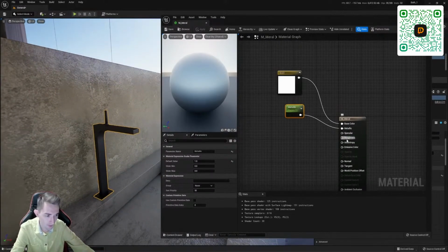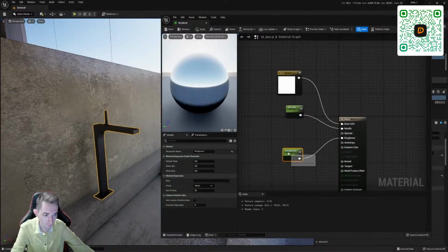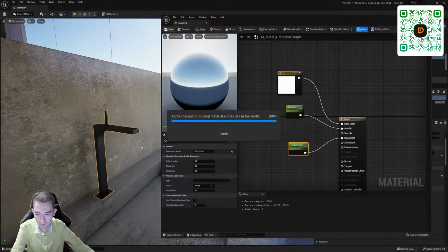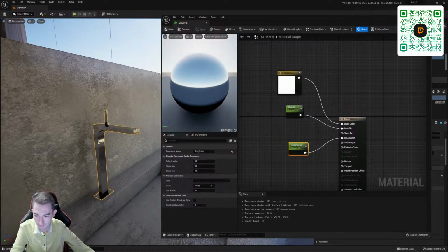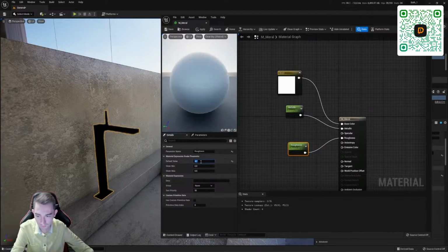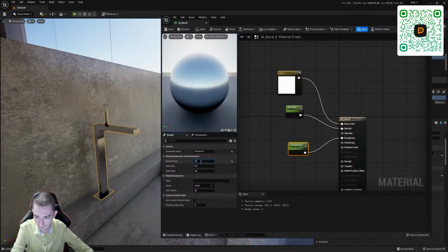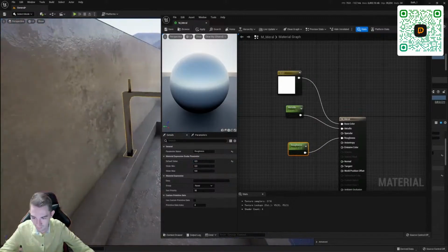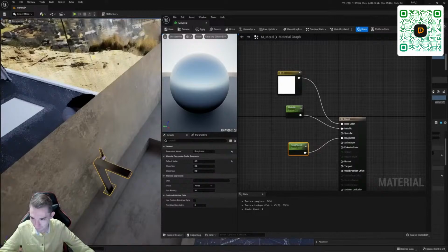Now we set the roughness parameter. We set the parameter, and already here we set up glossy. Now it's 0, it will be absolutely glossy. Let's see how it will work. Yes, but we don't need too glossy, we need less glossy. I'll probably put 0.3 like this. Yes, 0.3.